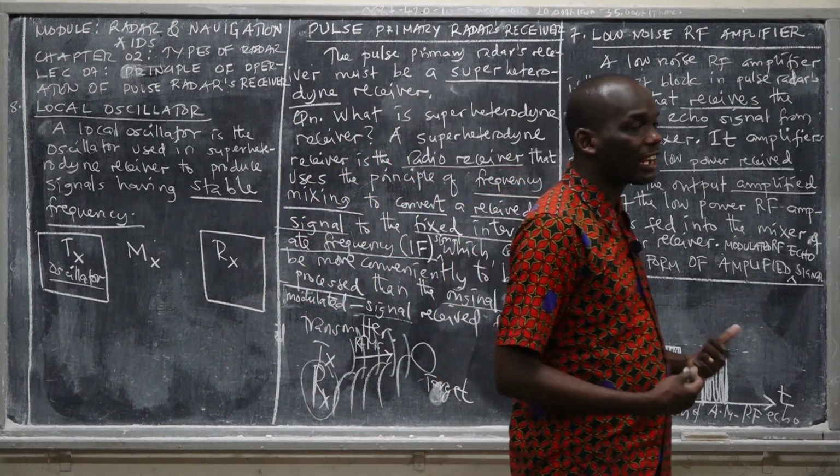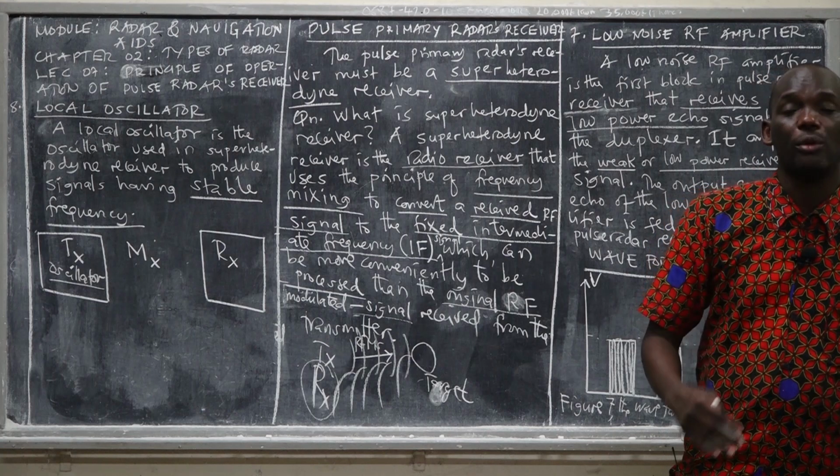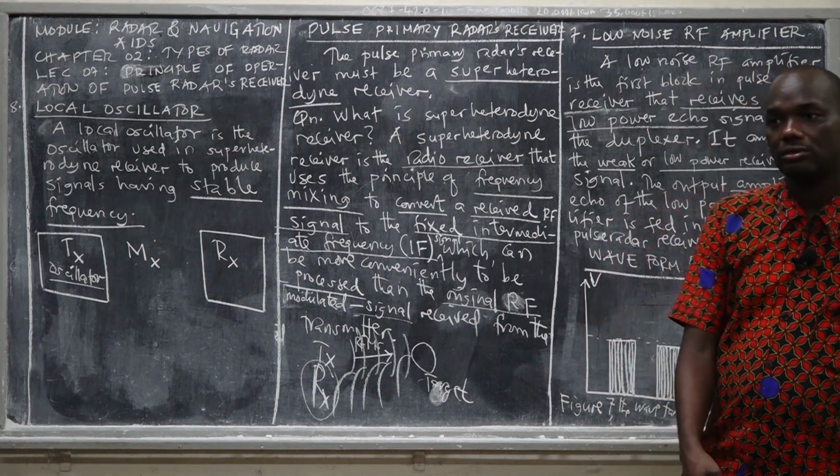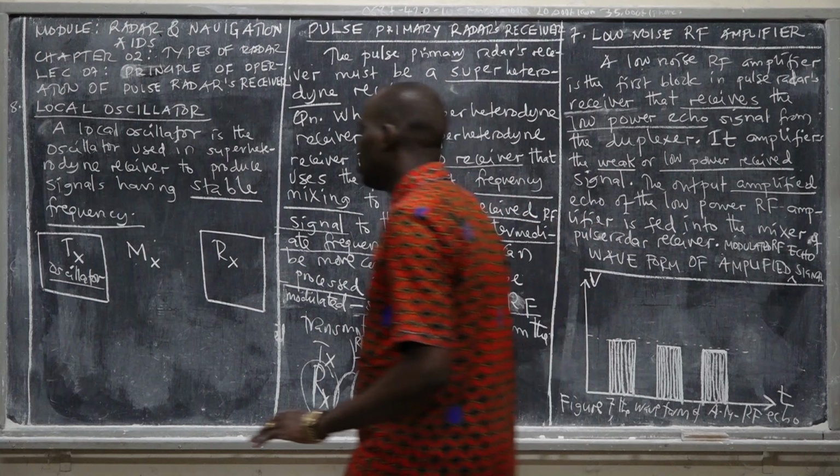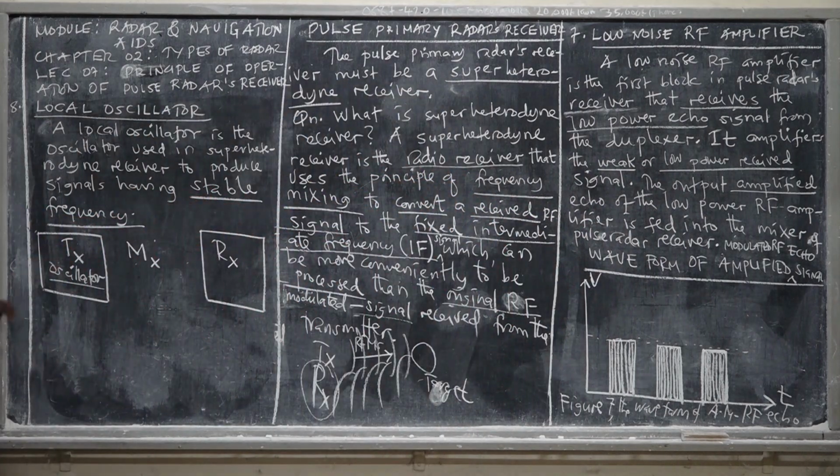So whether it's guided or unguided, in most cases for long distance communication, a carrier signal is important. This oscillator will produce the carrier signal, and then the carrier signal will be modulated with the information signal. Once we have a modulated signal, there's a process of amplifying, reducing the noise, and increasing the signal to noise ratio. Then this signal will be propagated into the medium by using an antenna, if it's wireless.